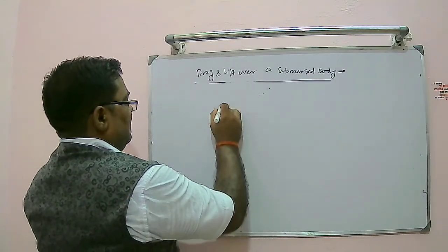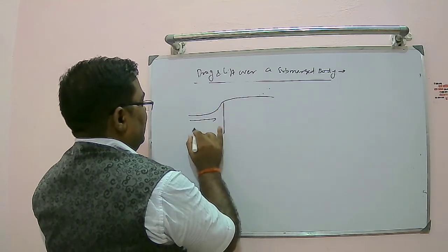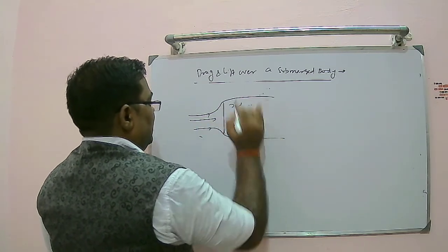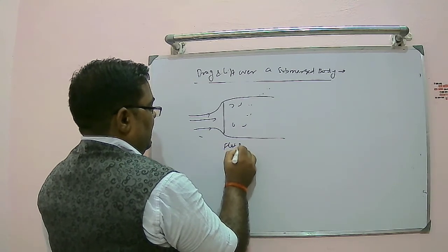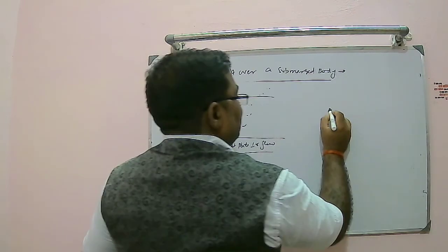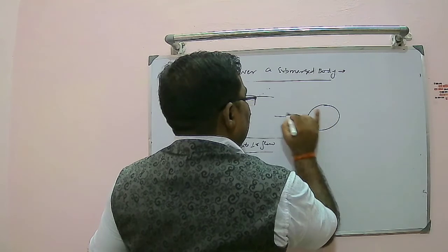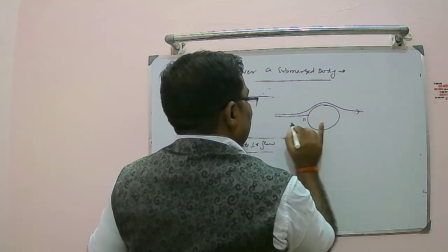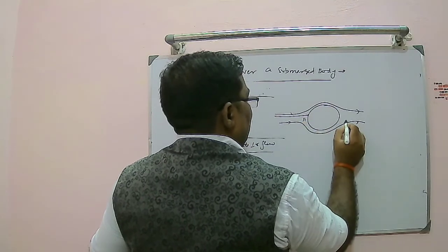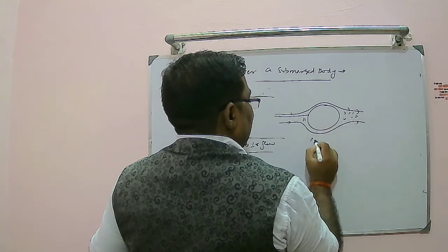One is the thing which we have got like this. In this case flow was coming like this and getting separated here. It was coming like that and separated from here. So here a large wake region is present. This is a flat plate, a flat plate perpendicular to flow. Second case, you consider a circular cylinder. Flow is coming like that. First stagnation point you will get here. Now flow will go like this and travel up to here, and goes like that and travels up to here. If you look here, some wake formation will take place. So this is a cylinder case.